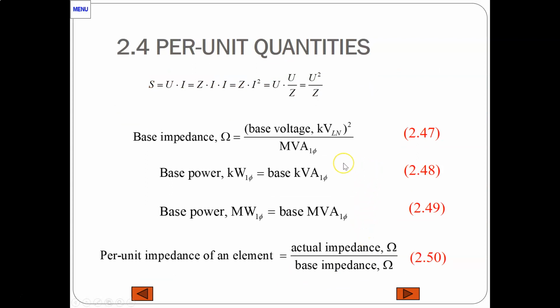To understand where this equation comes from, when you calculate the apparent power you have the equation of the voltage squared divided by the impedance. In the same way, you see equation 2 for the same, and we will also use that for 3-phase line-to-line voltage and 3-phase power.